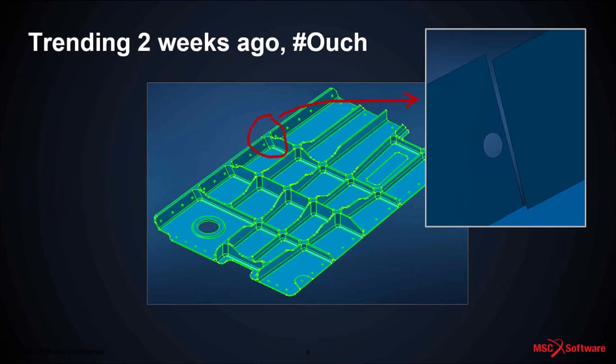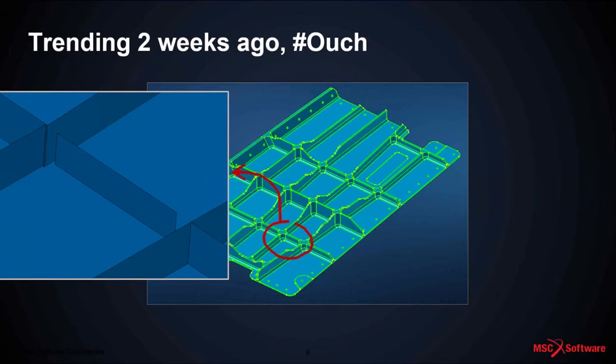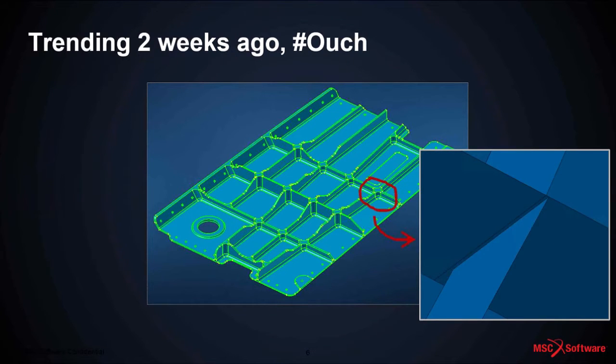We had a lot of misalignment in this particular model. A lot of surfaces did not line up per se. Sometimes the misalignment was because we had little flanges that were coming in that were slightly offset from one another. Maybe they had different thicknesses. As the example shows here, a little skinny sliver area would be little skinny sliver elements which would potentially produce poor finite element results. So I wanted to avoid that. It would be my engineering intent that the idealized shell representation would have alignment. Okay?